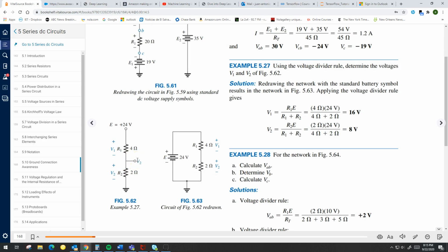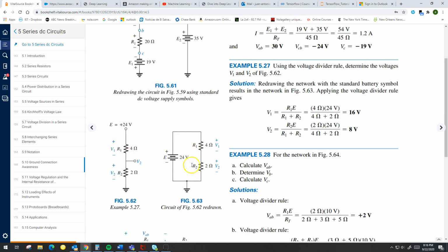Because that's what this indicates. So if we use Ohm's law, then you can say, well, the 24 volts is the one that's splitting between R1 and R2. So 24 is equal to V1 plus V2, right? And you notice that this is really the same circuit on the right-hand side. Maybe that makes it a little more obvious. The voltage 24 is just connected across R1 and R2.